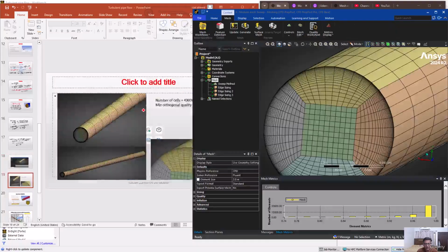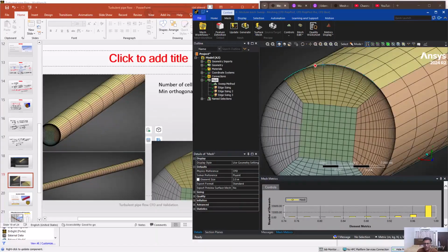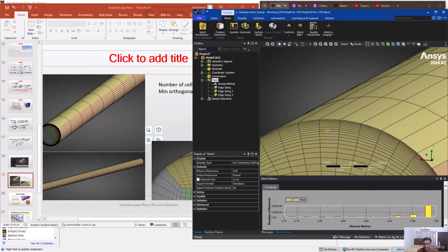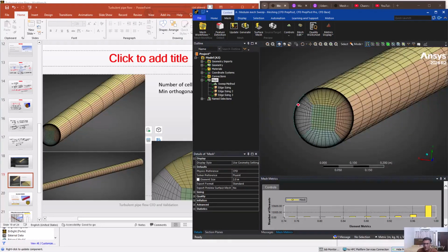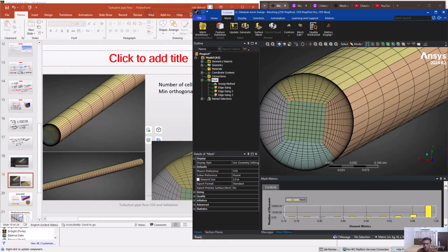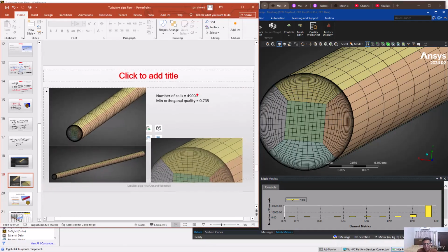Okay, compare here and you can feel this is exactly the same thing. Maybe we need to increase the number of cells on the circumferential edge. That is a part of the mesh independence study. That we will definitely do, and definitely we will go for more cells here. But keep this in mind, that if you go for more cells, then if you want to keep